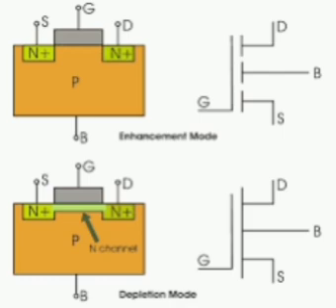Emitter injection efficiency gamma E is given by gamma E equal to IEP by (IEP plus IEN) for a PNP transistor. Gamma E equal to IEN by (IEP plus IEN) for NPN transistors, where IEP means emitter current due to holes and IEN means emitter current due to electrons. Base transport factor B is given by B equal to IC by IEP for a PNP transistor, B equal to IC by IEN for an NPN transistor. Current gain alpha in terms of gamma E and B is given as alpha equal to B into gamma E.